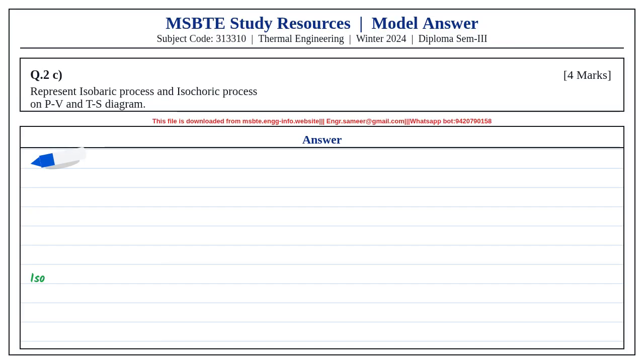At supercritical pressure, water is directly converted into steam without bubble formation. Superheated steam is supplied to the turbine. Its advantages are compact size, quick starting, high efficiency and suitability for large thermal power plants.